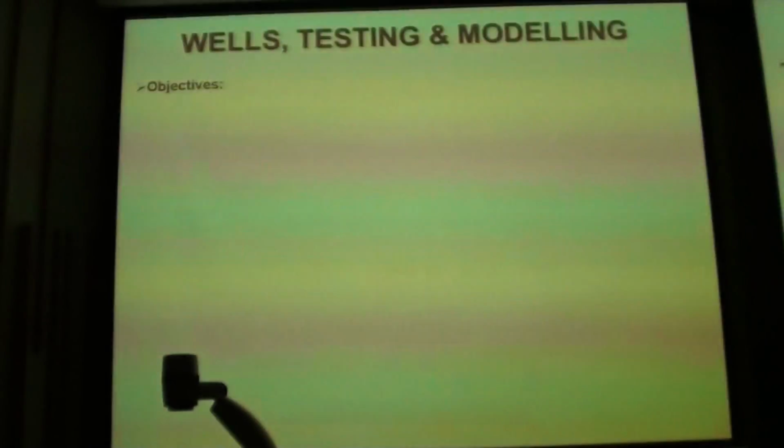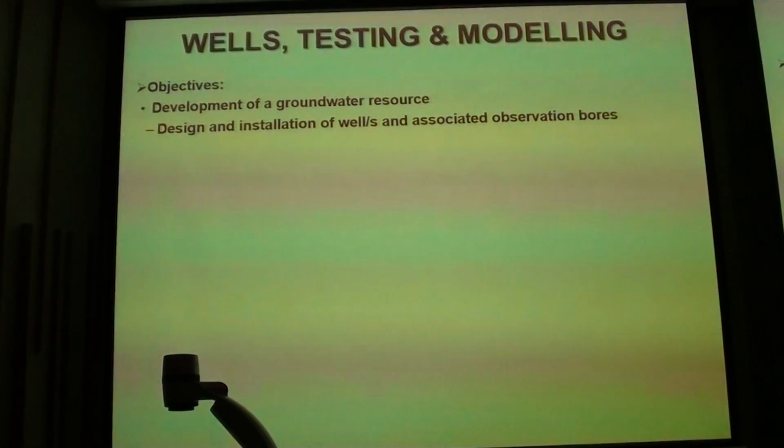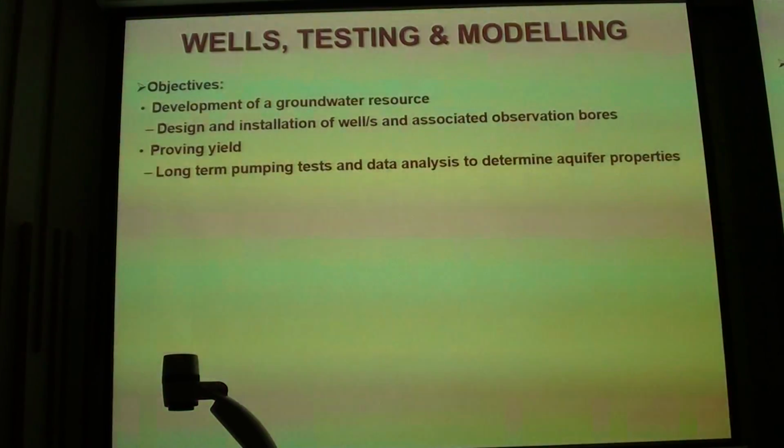It looks like we have an aquifer that's going to move water, hopefully produce lots of it, and so we cemented that in place. Alright, so now it's up to us to basically tell the client, yeah, it's okay, we think you can go ahead, and they'll give us the okay, and then we start designing wells, a testing program, run the testing program, look at the results, and then model it, and hopefully everything after that has gone okay. Nine times out of 10 it works pretty well.